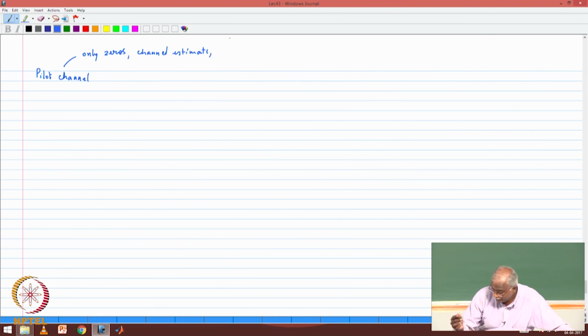The pilot channel has only zeros, no information. It's only used for channel estimation, so that you can do coherent detection. And what are the things that you are trying to estimate? You are trying to estimate the multipath, and the delays, all of that. That's the pilot channel. That's number one.